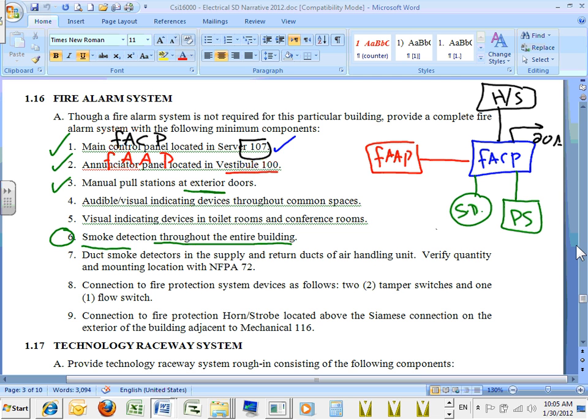Okay? So what the smoke detector does is sense the presence of smoke. There are different technologies. I'm not going to talk about the technologies, but there is a smoke detector. They have some chambers, guys. Anyway, there's a current that goes from one point to another point in that chamber in the smoke detector. If that chamber is filled with smoke, it interrupts the flow of current, and by interrupting the flow of current inside the chamber, inside the smoke detector, it activates the system. It sends the signal that, hey, there's the presence of smoke.